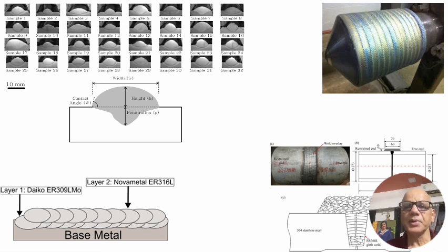Now these are the typical weld geometries what we are seeing it now. So if that angle is not maintained, as I said, then you will have something like this, very sharp. See, these are all which are not acceptable. Only the smooth ones which are having a good contour will be good, and if we get that, then your barrier layer, the first layer and the second layer will also have a very good uniformity.